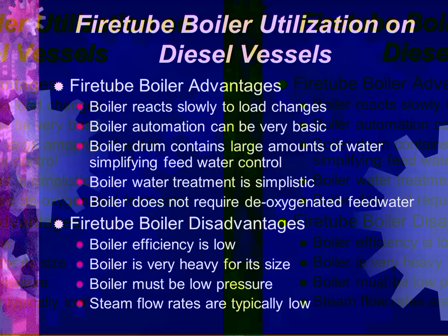So that's a big advantage when the designer is laying out the ship and the systems. This low pressure boiler does not require an expensive closed feed system, and the boiler water treatment is much more simplistic and less prone to the engineers making a mistake.